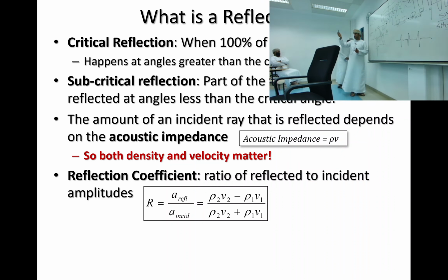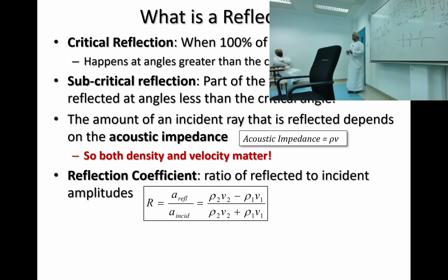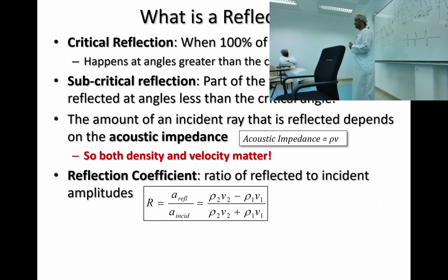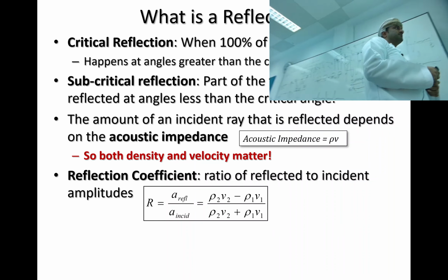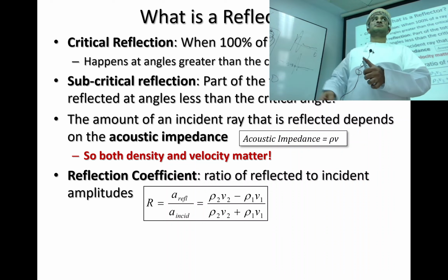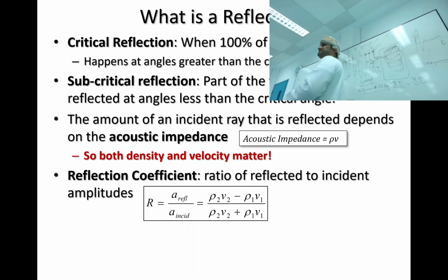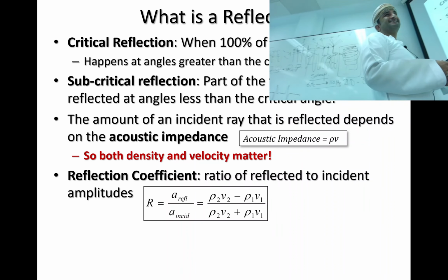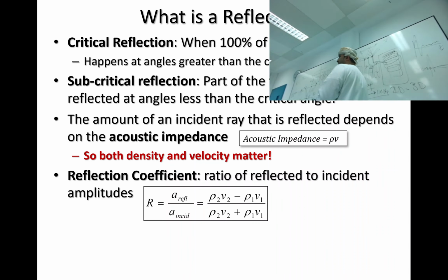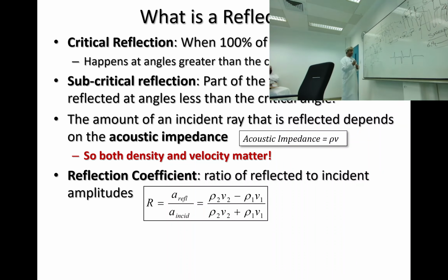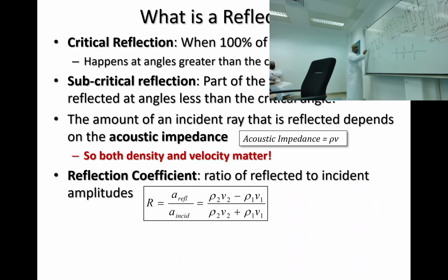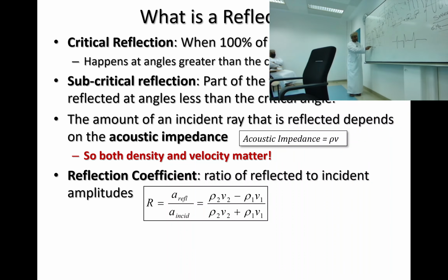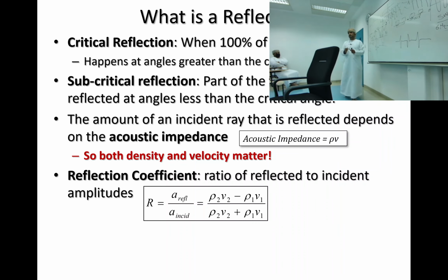That's the same: all the energy is reflected, but the geophone here reads it the opposite way. That is a 180 degree phase shift. That's what minus 1 means, the opposite of this. For example, if V1 with density 1 and V2 with density 2 gives me this, then if you reverse it, the rock that was here goes there, and the other goes below, it gives me minus 1.